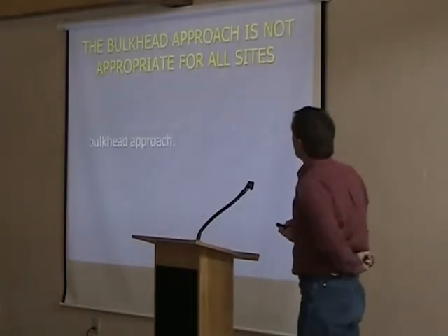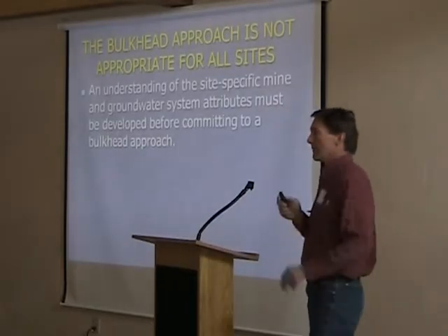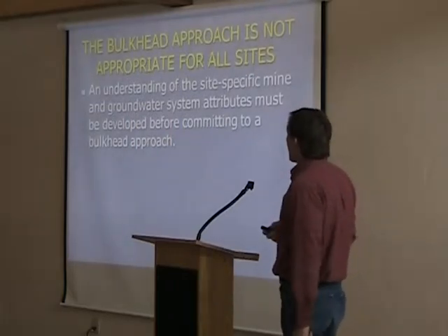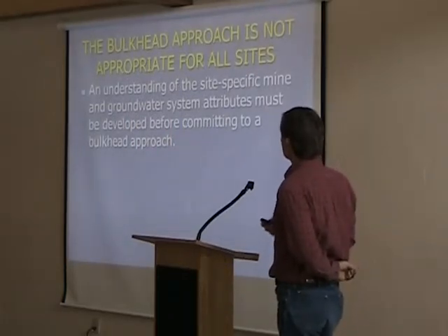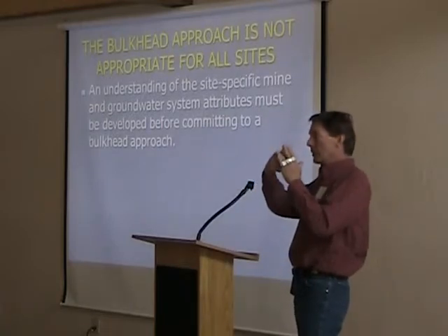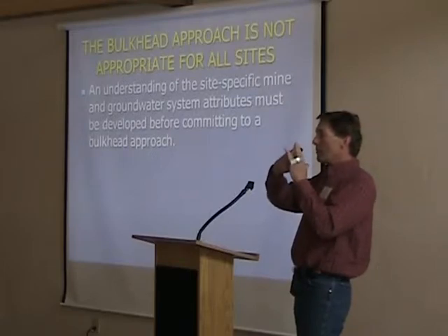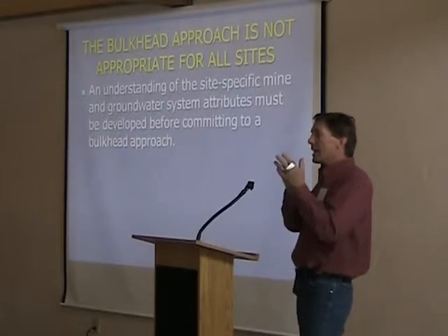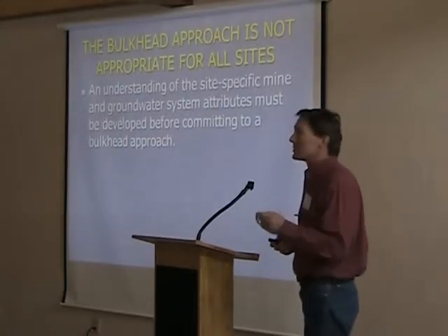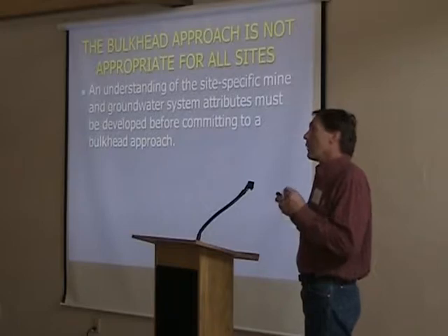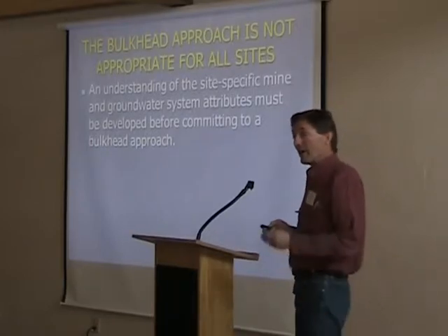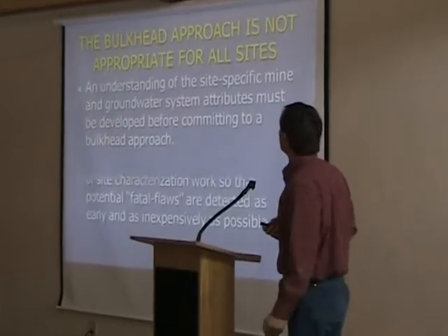So again, they're not going to work in all mines. They just aren't. Everybody says, well, why can't we just plug all these adits up and be done with the problem? You've got to have an understanding of the site-specific mine and the groundwater system that the mine is a feature within. Something was changed when we drove an adit or sunk a shaft. We changed that groundwater hydrology, and now we've probably got a short circuit going on. But you need to understand what's short-circuiting, where the water was before, what the water levels were before, and where the water is going to go if I put the plug back in the mine.